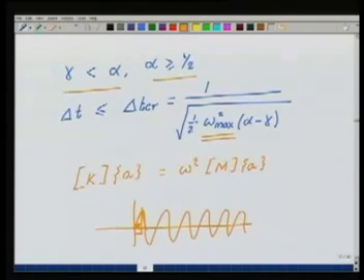And as omega max increases, I need to use smaller time steps in order to resolve these frequency components. Otherwise, my temporal error will become large, it may blow up, and then all the job that we have done in trying to do a very good approximation in the spatial regime will go out of the window. You will not be able to get accurate approximations in that case.